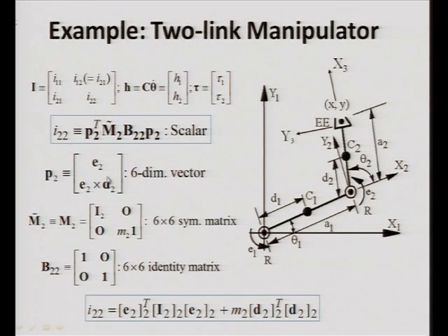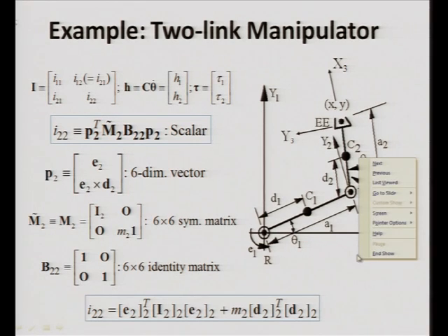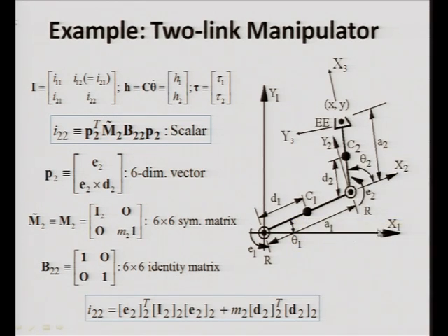So, now I apply this matrix multiplication here, and as we have seen for the single link case, it will be E2 written in frame 2. Everything is written in frame 2; the square bracket with subscript 2 means the representation in that frame. Where is my frame 2? Frame 2 is this one. And how is frame 2 set up here? Frame 2 is set up as if it is welded to the first link, so frame 2 is attached to the first link.